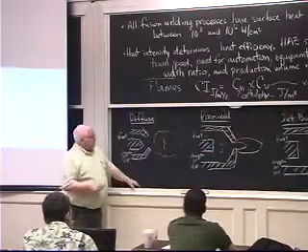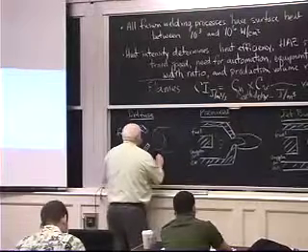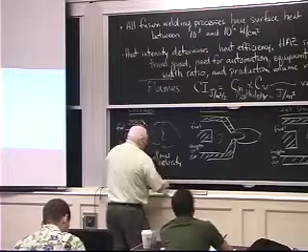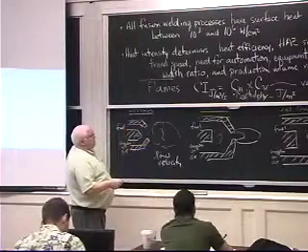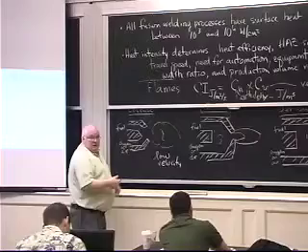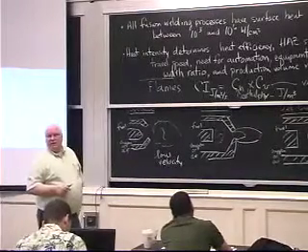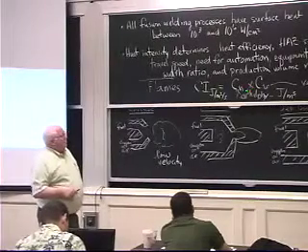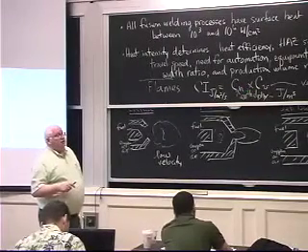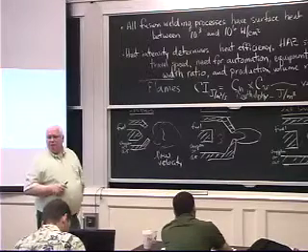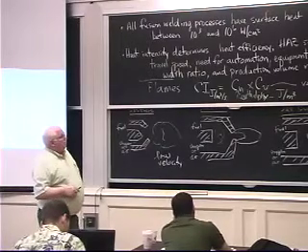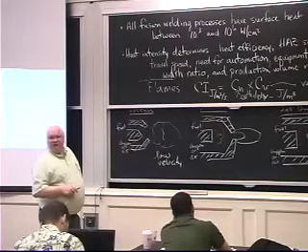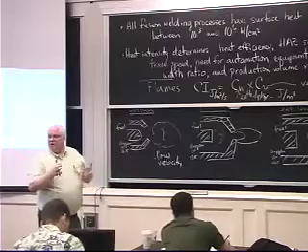The next level, and this is low velocity. And with this low velocity, even if I have a decent enthalpy, the fuel is a decent fuel. Paraffin wax is the same as ethylene, okay? C2H4 or something. CnH2n+2 is the official formula for paraffin, but it's also the same formula for polyethylene and other things. You have a reasonable enthalpy, but you have a lousy velocity because you're not burning things at their optimum ratios.